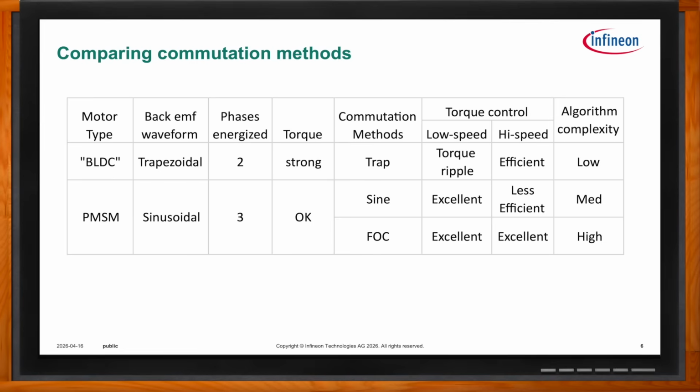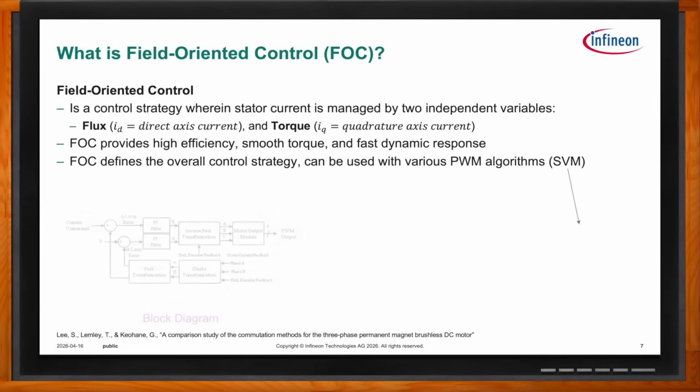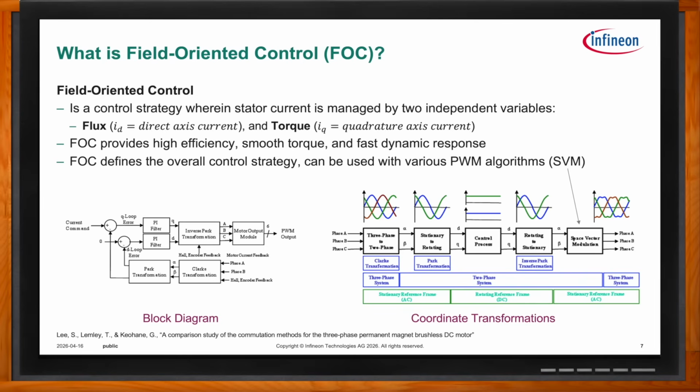Now let's get down to the bottom line here, where this is what we're really talking about today, is using what we call field-oriented control, or vector control, it's sometimes called, where you still get the excellent low-speed performance, but you can now get not only great dynamic performance, but outstanding high-speed performance. It's the best of all possible worlds, but it's a little more complex to implement. So we also need to talk about field-oriented control as well, right? Yes. Let me just mention that because, as I said, it's vector control, sometimes called, or field-oriented control.